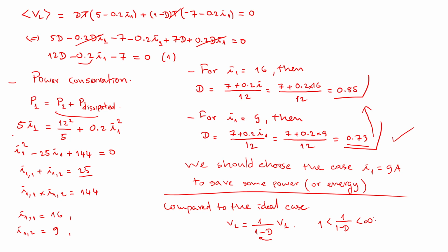It looks like that if you assume your boost converter is ideal, with no internal resistance in the input. You try to increase D, and you expect the output voltage to increase as well. But it's not the case, and you realize that at some point, no matter how much you increase D, the voltage at the output of the load cannot increase anymore.